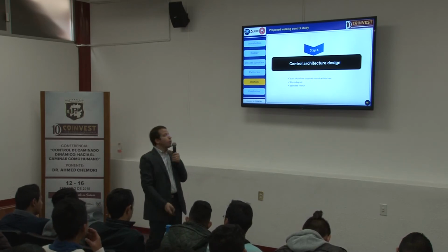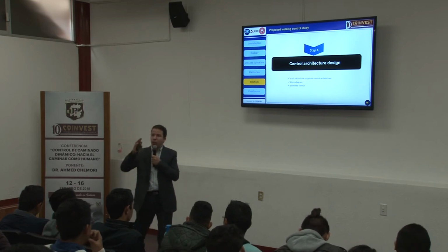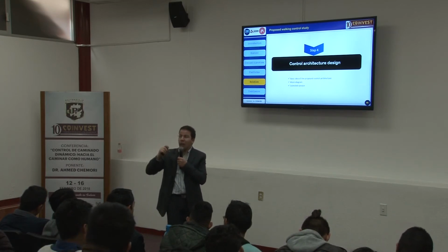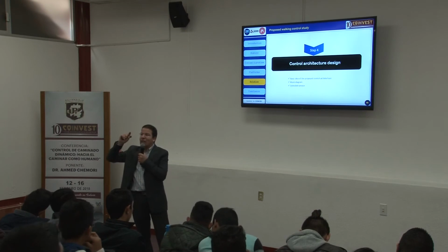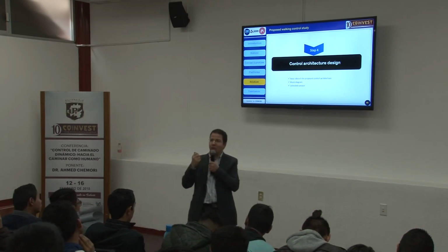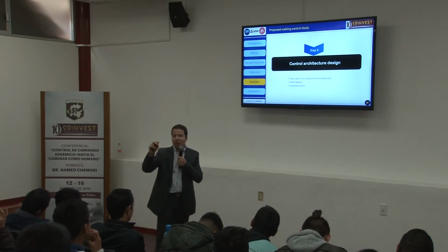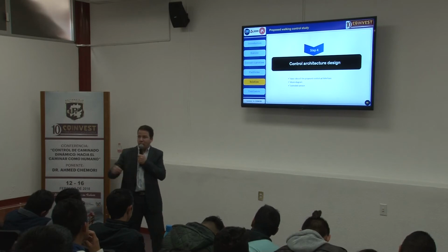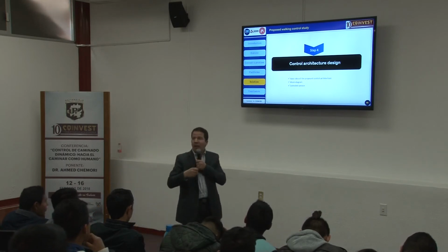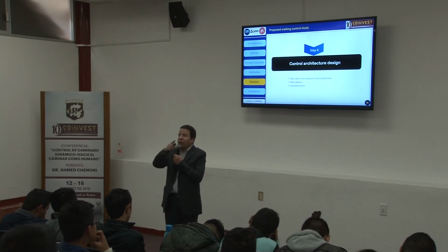So in our case, we try to develop a basic idea, which is very simple, which is hybrid, kinematic, and dynamic, and we try to use the minimum of data coming from the human walking. The minimum data that we have chosen are only two: the position of the center of mass, so the evolution of the center of mass during walking, and the relative distance between the two legs, between the two feet.